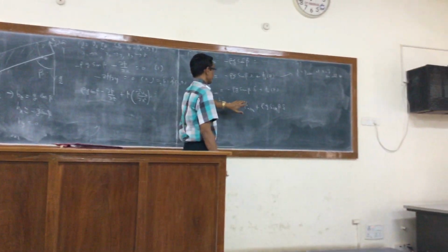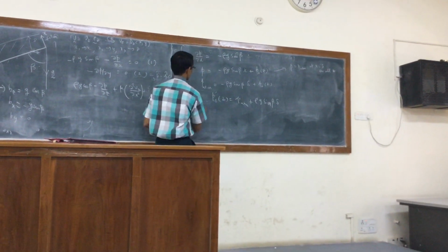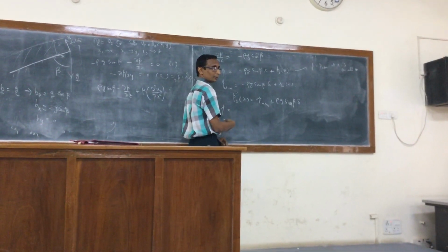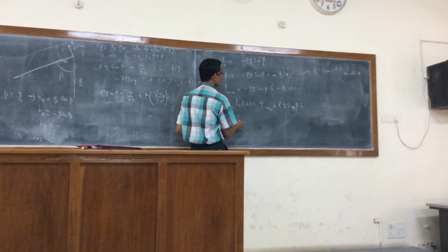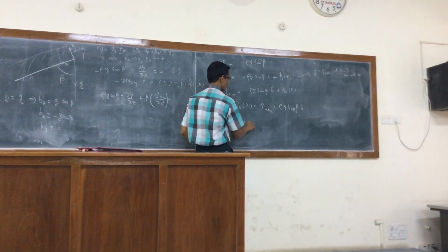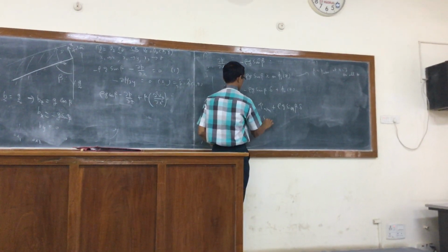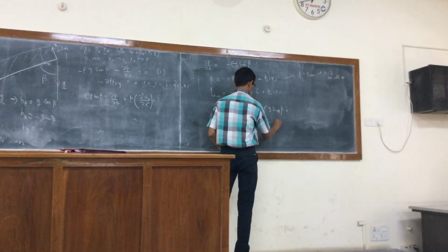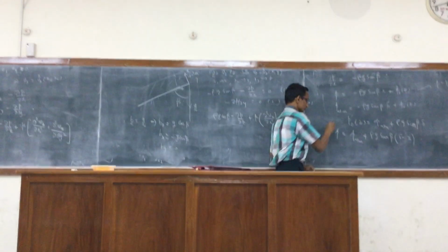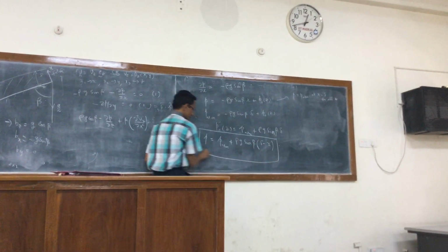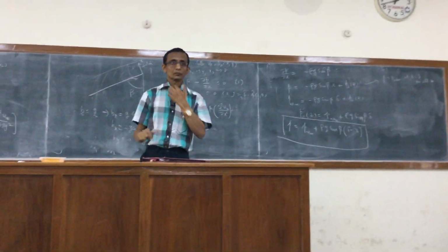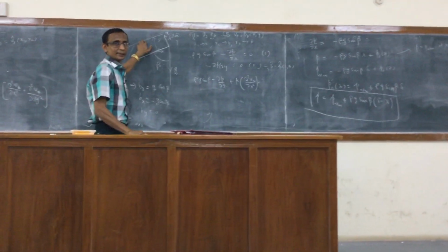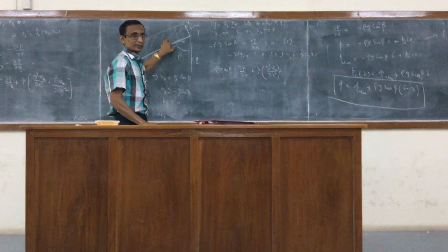So we get that, and then I can also find the pressure within the film, since that constant is given to me, P atmosphere. So I can write this as P atmosphere plus rho g sine theta times delta minus x. This is almost like a hydrostatic pressure, because delta minus x is the height below the surface, right?